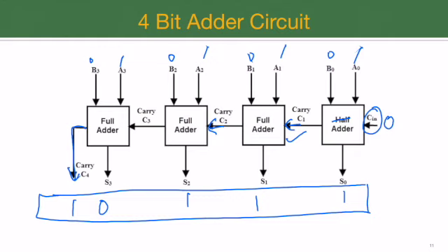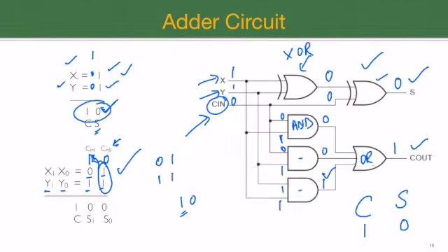just for a moment, let's look back and see what this full adder is constructed of. It's an electrical circuit consisting of multiple logic gates, as shown over here. So it consists of 6 logic gates. Also remember that it's not necessary that this diagram should be used. There are other ways of producing the adder circuit. If you look on the internet, you will see that there are multiple ways of producing the adder circuit. Specifically, the NAND gate is called a universal gate, and most of the circuits are produced in the form of NAND gates. So you will be able to see that representation as well.